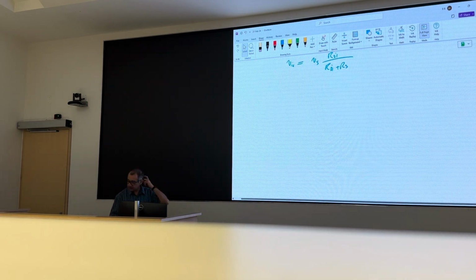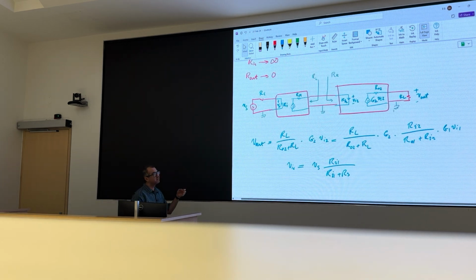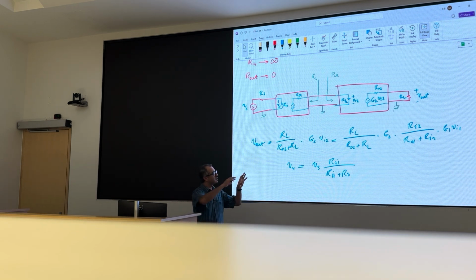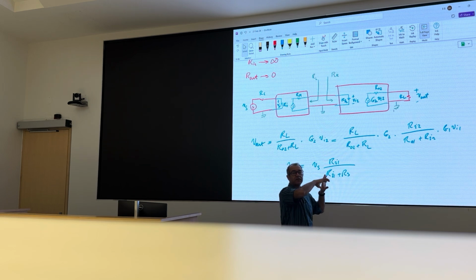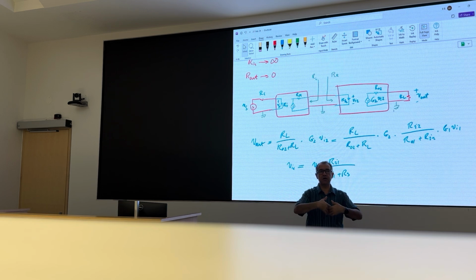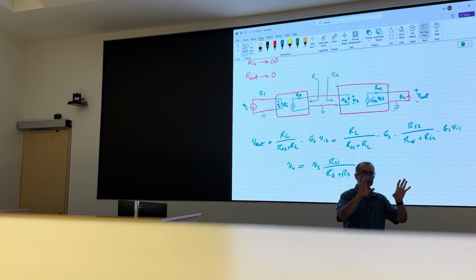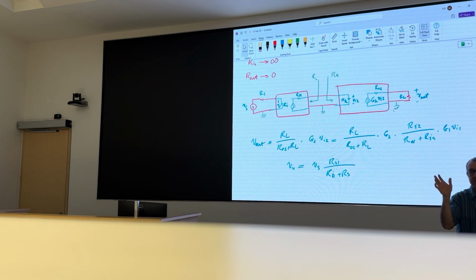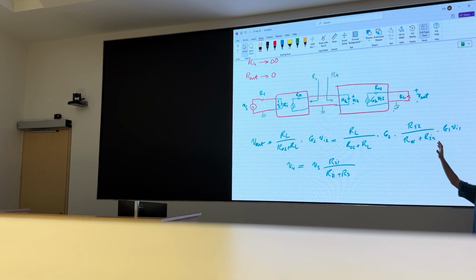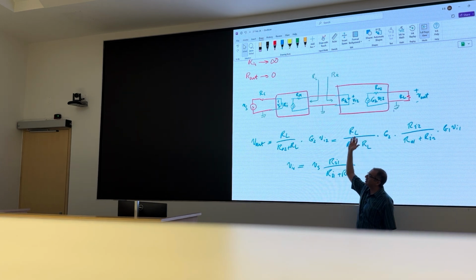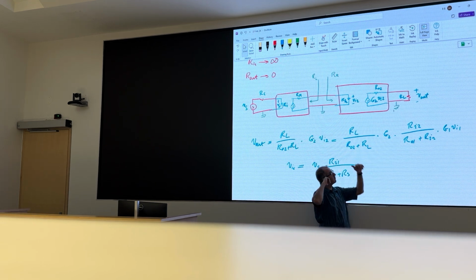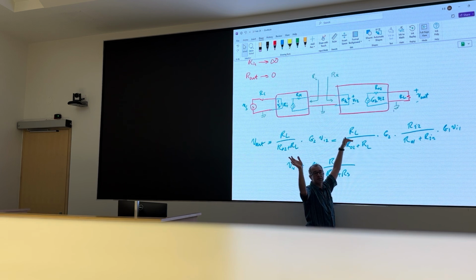Let's just see how we calculate that resistance. I hinted at it. It's the Thevenin resistance. So once we are dealing with these amplifiers and we're dealing with linear amplifiers, we're using the small signal model. Your circuits are linear. From now until the rest of this course, whenever we talk about small signal and amplifiers, life is easy because everything is linear. No e to the power of this and that. So all I need to do is find the Thevenin equivalent resistance when I look back, or when I look this way. That's all I need to do.